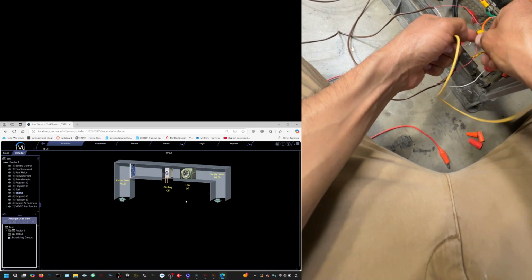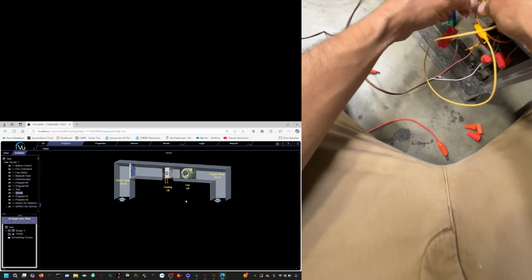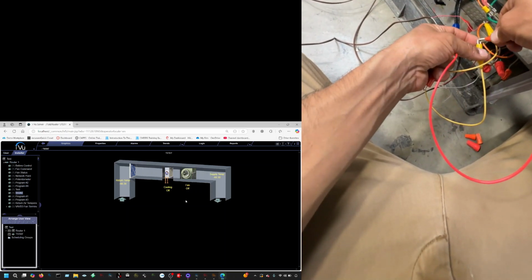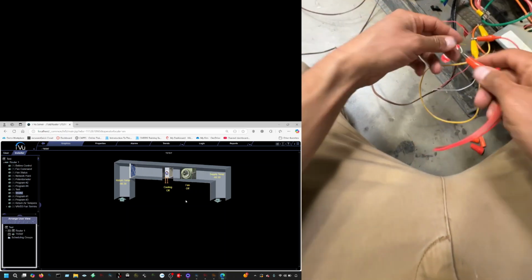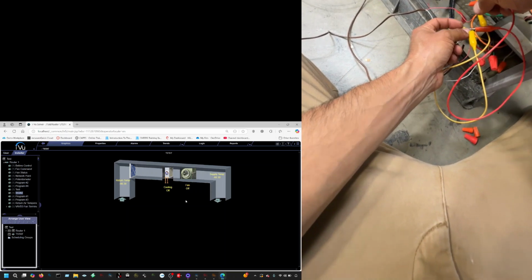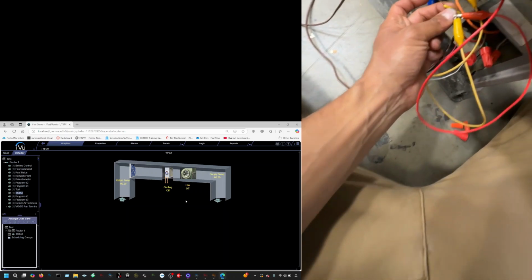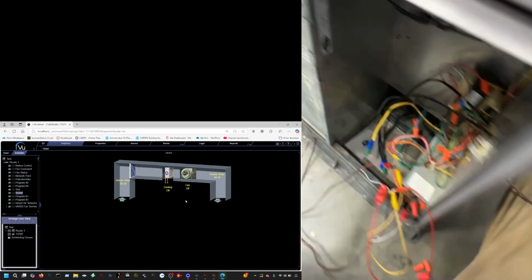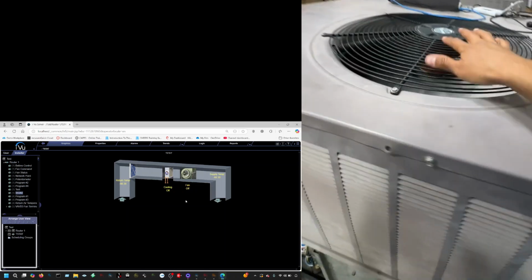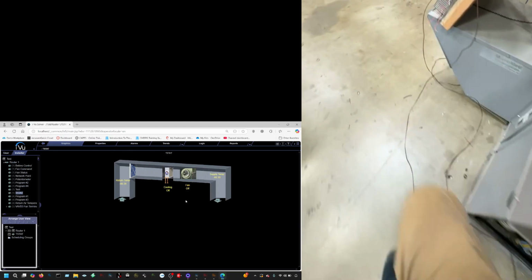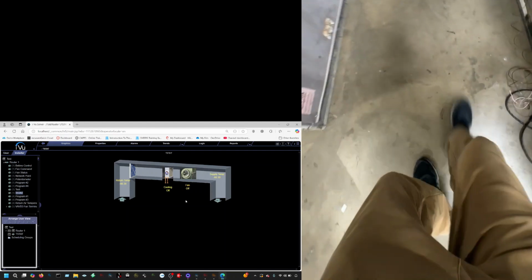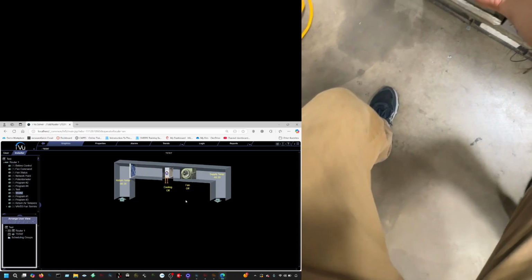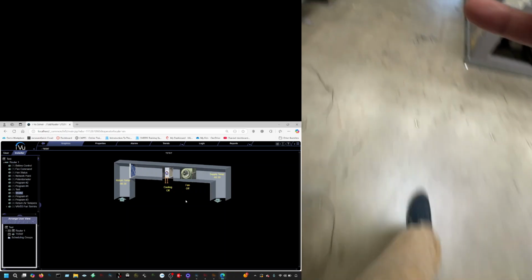I'm going to go ahead and get my power. Go ahead and send 24 volts to my reversing valve. And then this is what's going to engage and turn on the compressor, by jumping the R to the yellow wire. So let's go ahead and do that. Okay, so you can see it's on, and now we're cooling, right? This is a return. That's the supply, and I can feel it coming out cold. That's what a thermostat does.